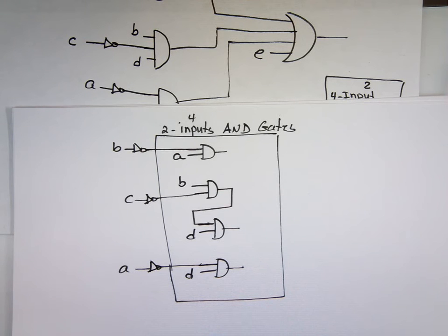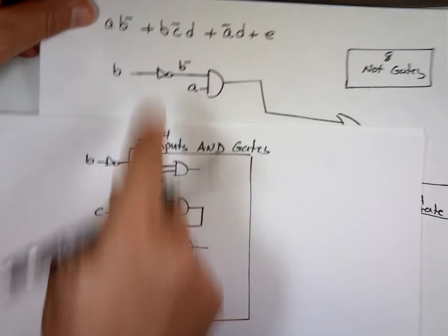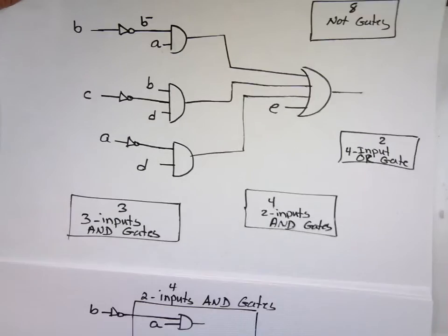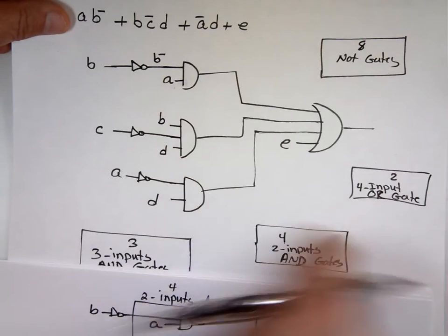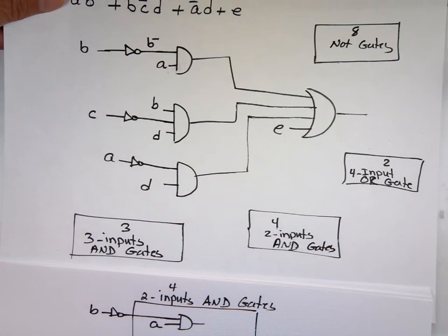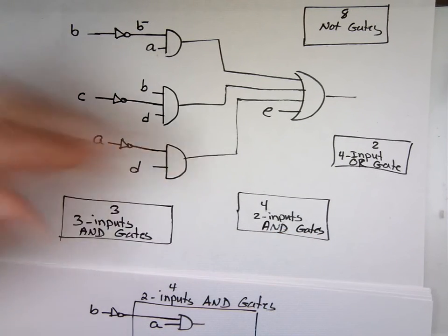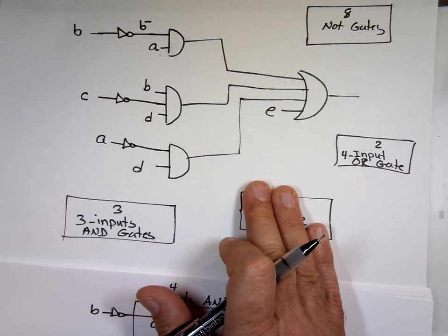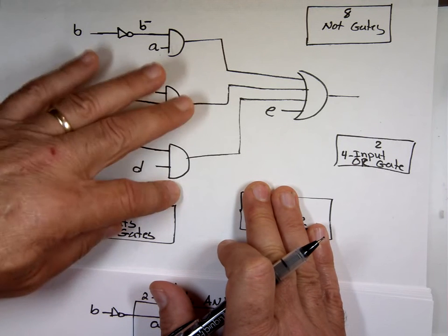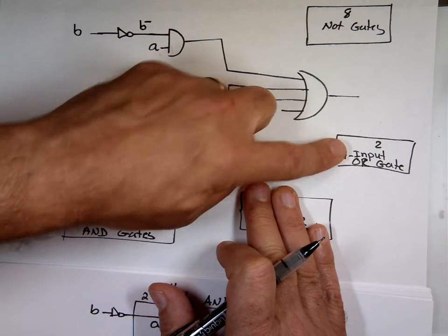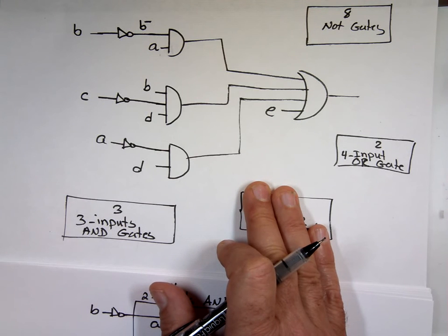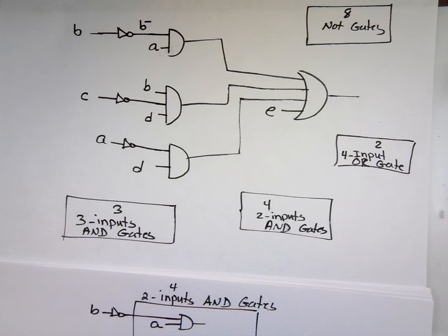That's where Boolean algebra comes in, if I can simplify the expression or not. Mathematically, I might not be able to simplify it, but at least in my design, instead of using a chip, a chip, a chip, and a chip, 4 of them, I can eliminate this or that, see what the price is, which one's cheaper. If this is cheaper, take this one out and use that design. If this is cheaper, drop this one out and use the previous design. Use these to make up this. I still need to get the OR. I have those, and I got the NOT gates. I might even look for a third option, which we'll discuss later.